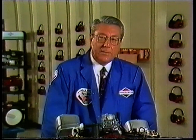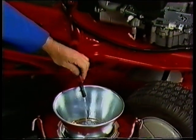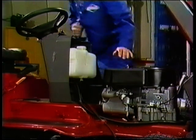If all components test okay, it's safe to assume that the leakage problem was caused by dirt or debris. To correct these problems, it's very important to follow the next few steps carefully. Start with the fuel supply. Drain the fuel tank completely and inspect it for debris, dirt, or scaling. Depending on what you find, you may clean the tank or decide to replace it.